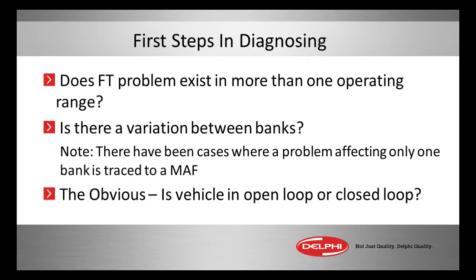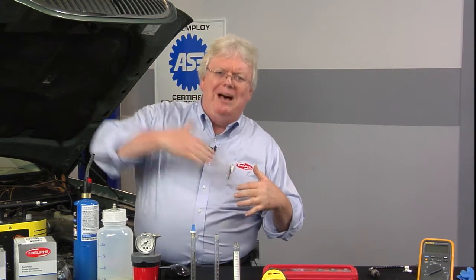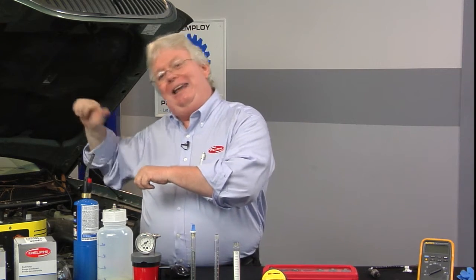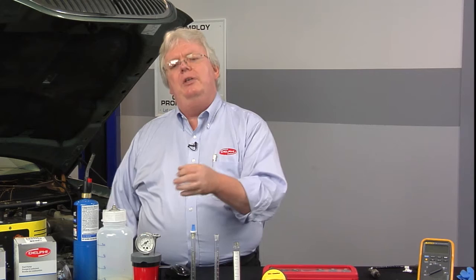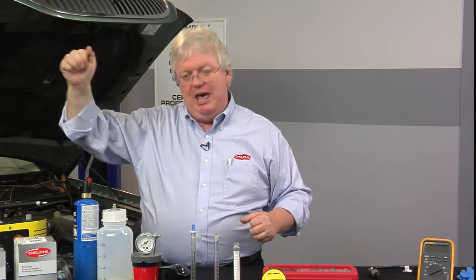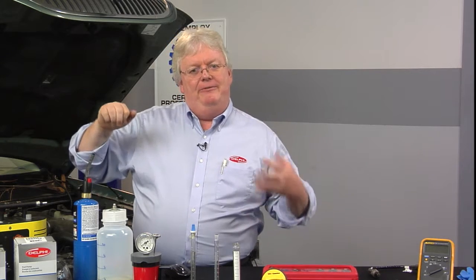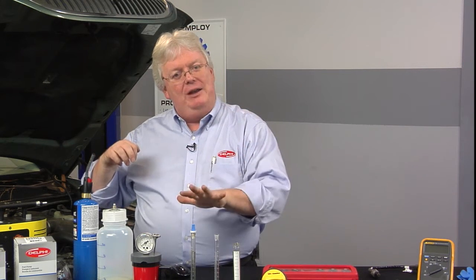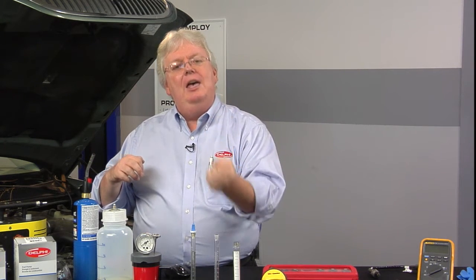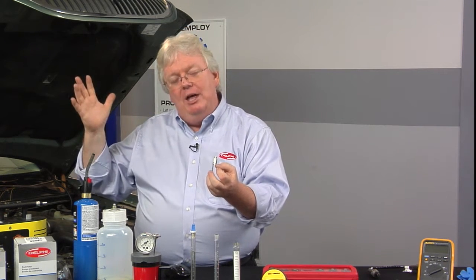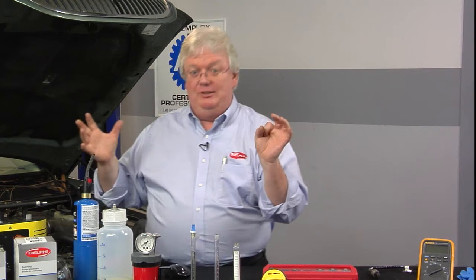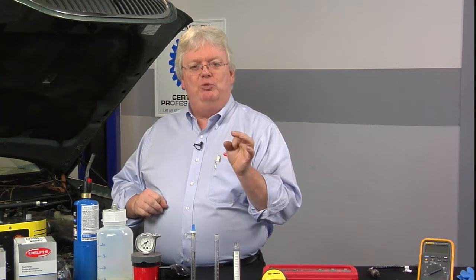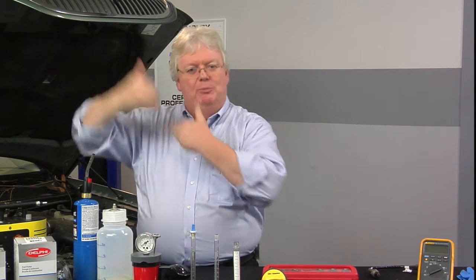So you see, let's say positive 20%, we're adding fuel, but then you go above idle. You get into 1500, 2500 RPM. You need to run different ranges as you idle it in the shop, rev it up, and go on road tests and so forth. Watch what the trim is doing under different conditions. As you rev it up, and that trim goes from a positive 15 or 20, adding fuel because of maybe a vacuum leak, that number comes back down again because vacuum leaks don't have the profound effect on air fuel management when you get above idle. A little tiny hole in a gasket or a vacuum hose that has fallen off, whatever, is a very small percentage of overall air usage when that throttle is open quite a ways and we're pulling a bunch more air in.